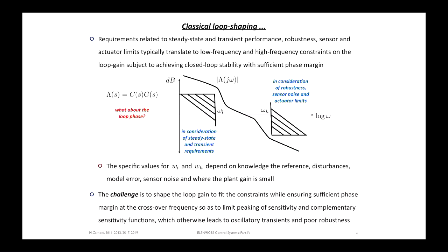And we've related that to how much oscillation there is, how well damped the closed loop response is. Okay, so clearly the closer these are together, the steeper the transition will have to be. And as we'll see later on, the steeper the transition, the worse the phase margin. All right? So control design becomes very, very difficult when these are close together. But what does these being close together mean? It means that we can't really separate out our competing objectives, the ones that are telling us to make it high gain and the ones that are telling it to make it low gain.